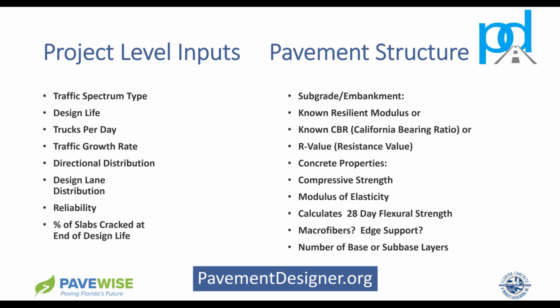So anyway, your subgrade there is embankment, but usually subgrade is the virgin material, but in Florida it can be embankment. But of that, you get the information more than likely from your geotechnical engineer, either an in-house geotechnical engineer, or you have an outside geotechnical engineer that writes you a report. And in that report, they may give you the resilient modulus.